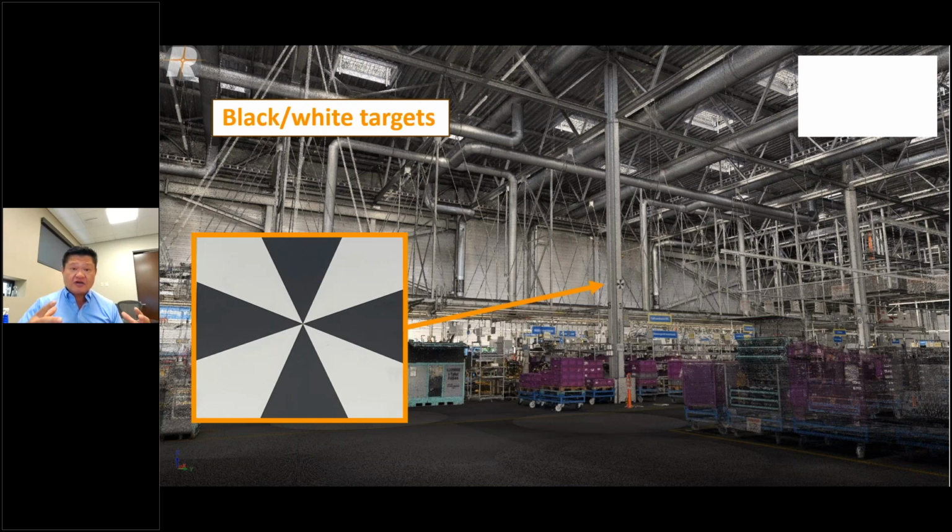The scanner itself internally has an IMU and a differential GPS, so you can get correction from a VRS network. Now, when you're driving down the road, I can see you placing these targets on the side of a building or maybe on a curb, and the scanner can then recognize the targets. But of course, there is more to come with that, from testing that I want to be doing in the next few months. And I'll do a webinar on that as well.